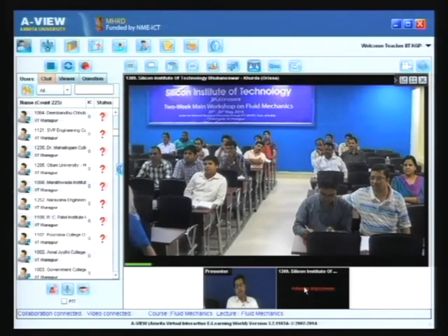No, you see that the system, by its definition, has constant mass. Whether it is a reactive or non-reactive system, if you do not allow mass flux across the system boundary, then the mass of the system will remain the same. This is the definition of the control mass system or closed system, which we usually just call the system. Its characteristic by definition is that its mass remains constant, because there is no mass flux across the system boundary.